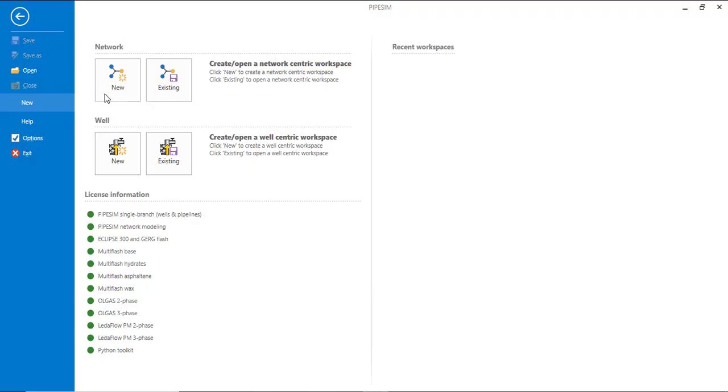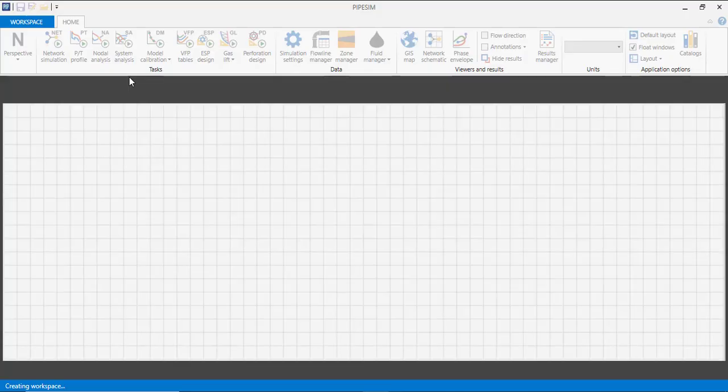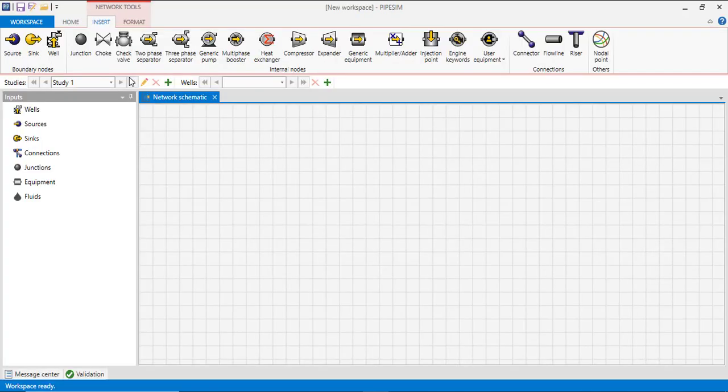So we will start from the network system, new network. Let's create a scenario in which you have a pipeline somewhere around 3 to 4 kilometers that is underground, and after that it enters into a station where it is above ground. As I stated earlier, we will see how we can model both, because the ambient temperature of the underground and the above ground line cannot be the same.